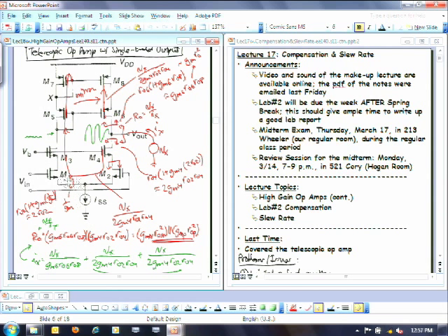Does that make sense? Everyone understands that the AC voltage is 0 here, right? No one's got a hang up thinking, wait a minute, don't you have a VGS dropped across here? Anyone with that hang up? It's reasonable to have that hang up, so if you have it, raise your hand, and then I'll say something about it. Because when we're talking about AC, you don't see the VGS here, you just see a 1/gm resistor there, like in the T model.